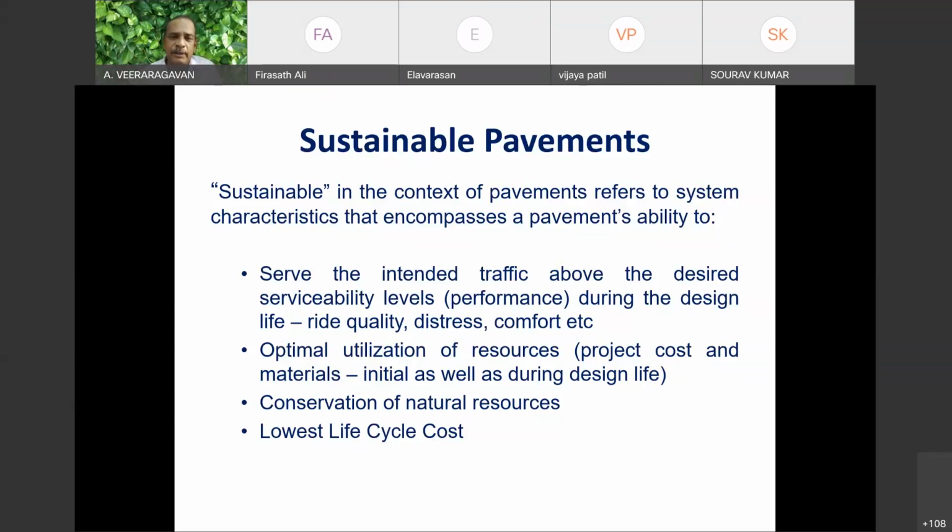A very bad road can have 2500, and with the passage of traffic, this roughness value will increase from 2500 to 3000 to 4000 to 5000 to 10,000 to 15,000. So it keeps on increasing. As the roughness increases, the vehicle operating cost also increases several fold. So what do you need finally? I need good serviceability, good performance. What else do you want? I don't want to see cracks in the pavement. I don't want the pavement sheared and rutted on the surface.